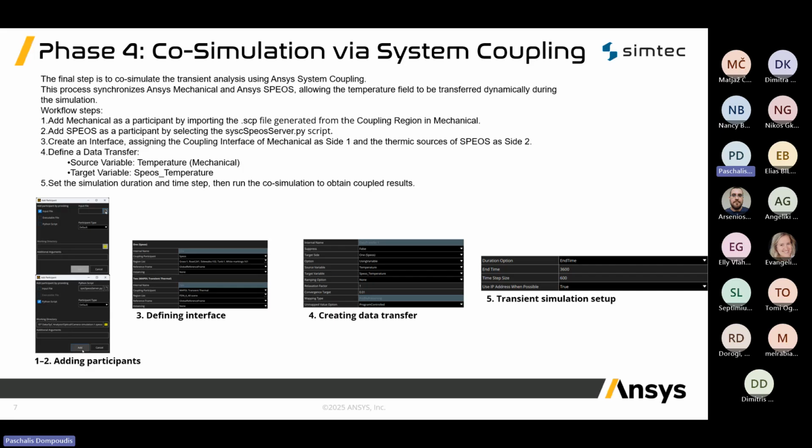When we start the simulation, System Coupling automates the entire loop. At each time step, Mechanical calculates the new temperature. System Coupling passes that result to SPEOS, and SPEOS generates the updated infrared image. This process repeats until the full simulation time is complete.